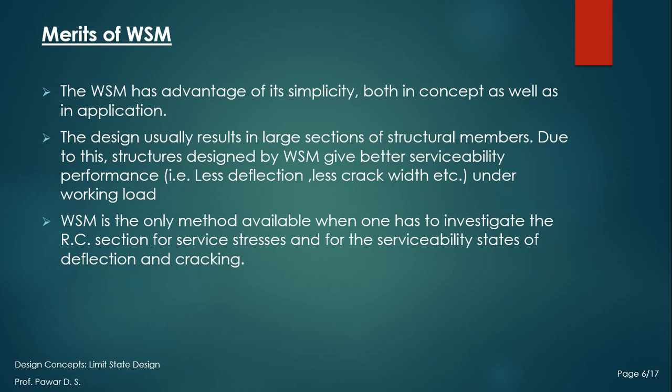And there are various merits of the WSM also. The WSM has the advantage of simplicity, both in concept as well as in application. The design usually results in large sections of the structural member, and due to these large sections designed by WSM, there is better serviceability performance, less deflection and less crack width under the working load, because of the heavy sections with large depth, so ultimately you get less deflection and less crack width.